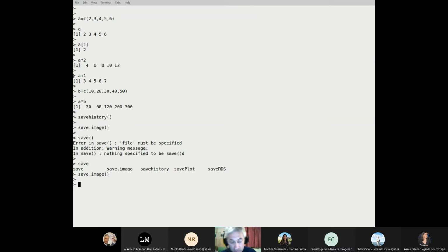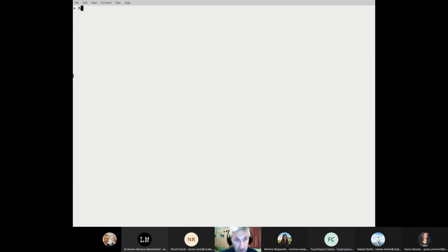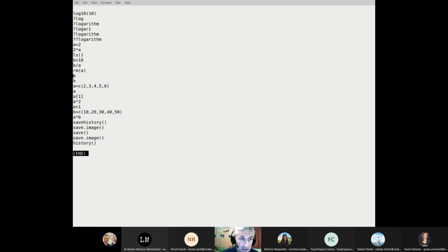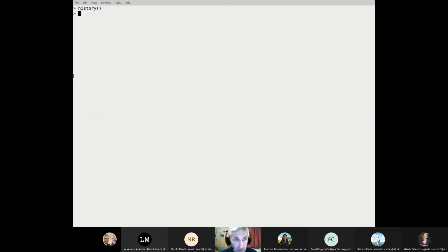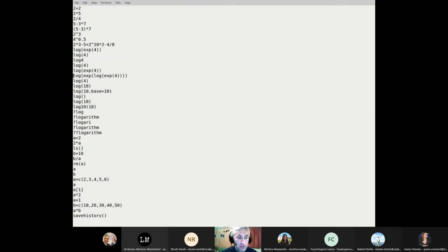So, for instance, let me show you the power of the history. If I just write history here with no argument, you see I get the list, it's not really full, of what I did today. It is extremely useful. If I want to get the full list, I need to increase the number of entries, 100. This is the full list of what I did today, which is very interesting because you can save it with the command save history, which is perfect.